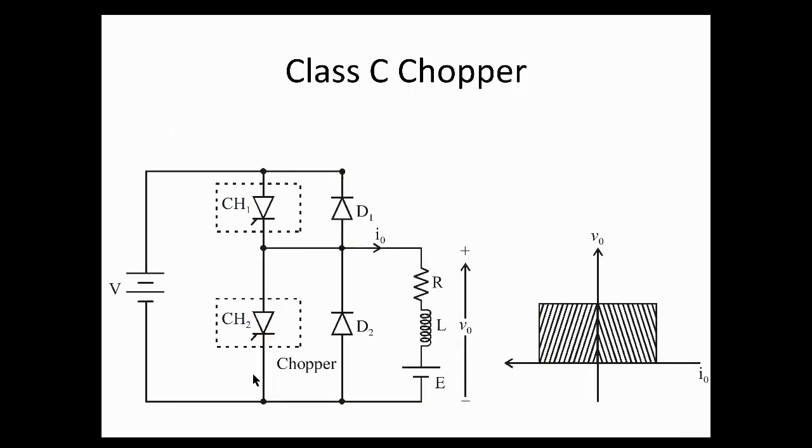What you have here is a short circuit, right? Turn the two of them on at the same time, short circuit. You don't want that. So these two choppers should never be turned on at the same time. When one chopper is on, the other one must be off, right?